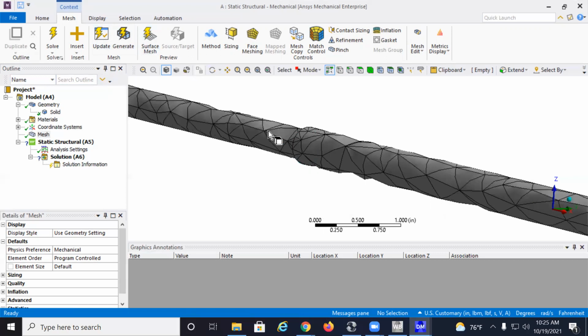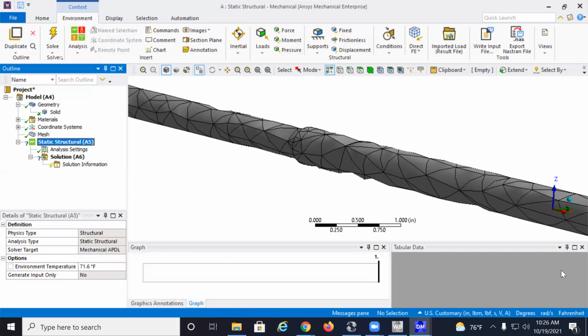So now I have a mesh, we have elements, we have nodes, and we are ready. We can now start writing the element stiffness matrices and assemble the global stiffness matrix. But in order to have a solution, we need to define boundary conditions. Otherwise, my matrix is singular and there is no solution. So I go to static structural.